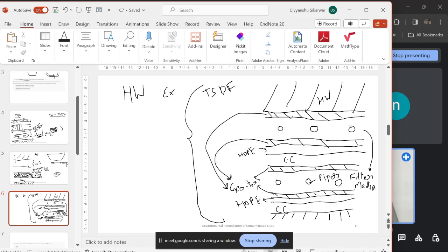So what is the use of the geotextile layer here? This geomembrane. Sir, what will be the use of this geomembrane here? If we put hazardous waste above the gravel, then also leachate will come out here, and from here these lateral pipes will take the leachate outside. But why did we put a geomembrane here? Because it controls that fluid. That is why, sir, that geomembrane.